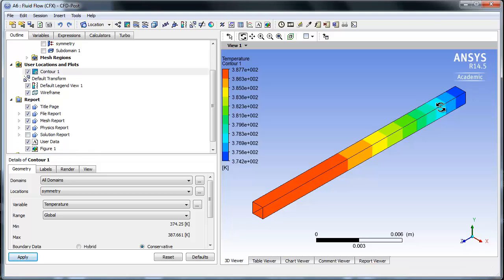Okay, and I'm visualizing that I have the coldest temperature at my starting point, z equals 0, and the temperature increases as I move through the domain, and then it's hard to tell what's going on here due to just the gradient. This is one of the shortcomings, I guess, of a contour map. I am always a stickler for making graphs as readable as possible, and dealing with Kelvin and with this scientific notation, that's not very readable.